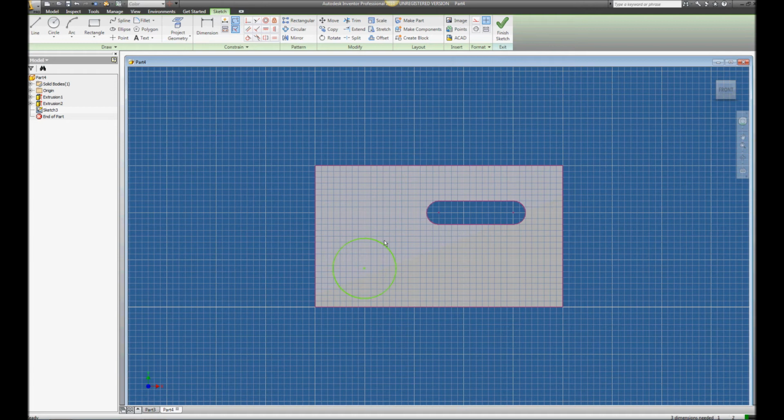Okay. So looking on page 3, D10, we need to grab our dimensioning tool, dimension the center to the outside, drop our dimension down here, and it's telling us it is our plate width, D1 times 0.25 or quarter. And hit OK.